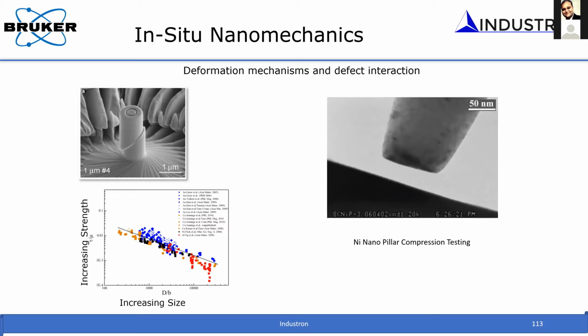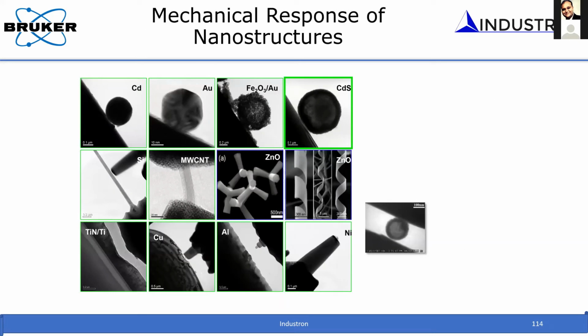So for example, in this pillar, this is about 100 nanometers. When the dislocations move, if they go to the surface and disappear, they're not going to multiply. So all the dislocations move out of the system and go to the surface, create a surface step, and don't multiply. That's why this material is getting harder and harder, and becomes less dislocated. You have just exhausted all the dislocations, so it becomes harder and harder. So we were able to explain that by doing experiments inside the TEM.